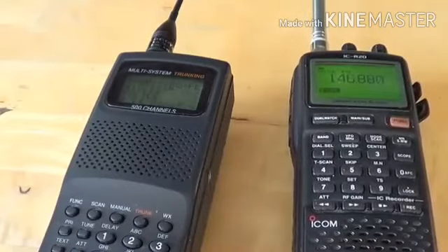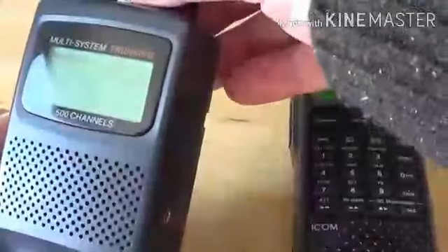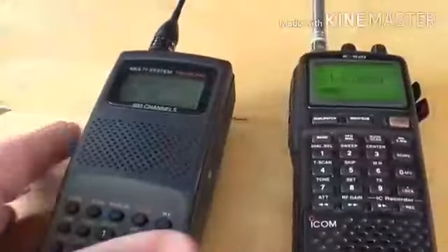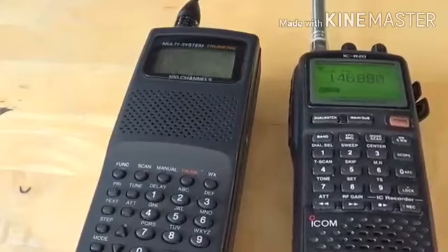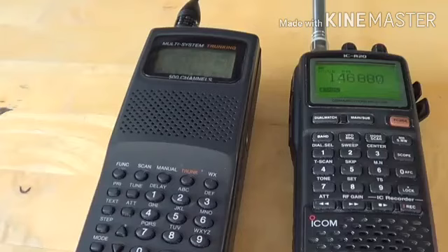Second of all, squelch is there because the receiver will not scan unless it doesn't see a signal. And the only way for the radio to see there's no signal is by putting the squelch at a certain level. By putting the squelch at this certain level, you'll be able to let the receiver know when there's nothing, and it's going to actually know when there's a signal.